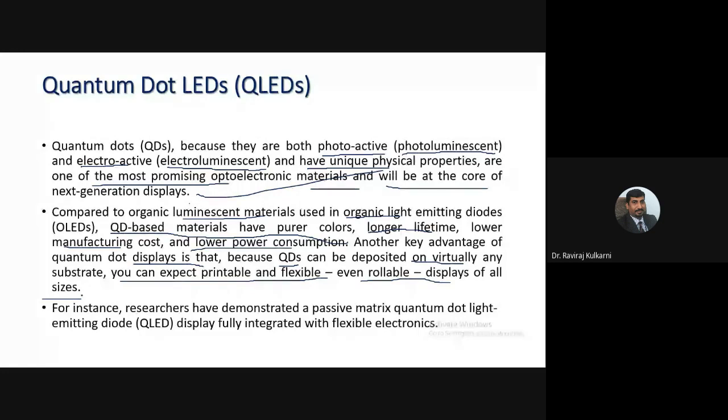Even OLEDs can be deposited, but the problem is they may decompose, undergo thermal degradation, or photo degradation. That's another problem. But QLEDs are not like that. They will not undergo degradation easily because they are inorganic compounds, metal oxides, and very stable.